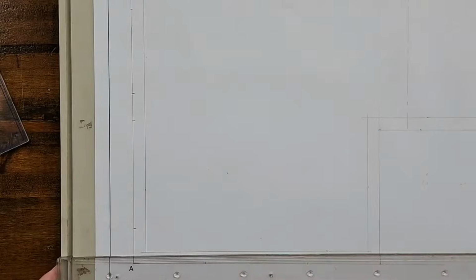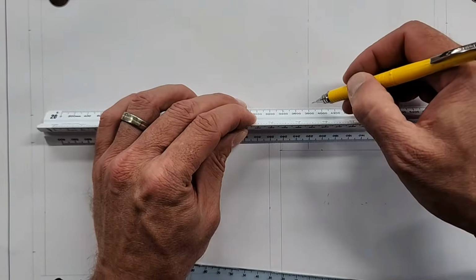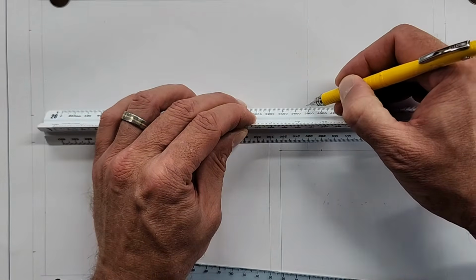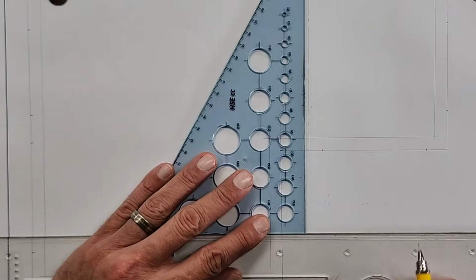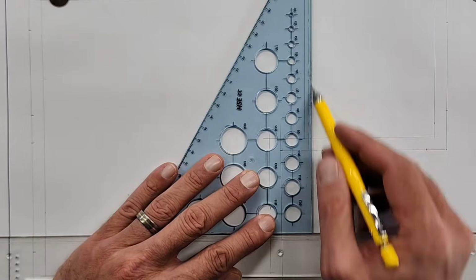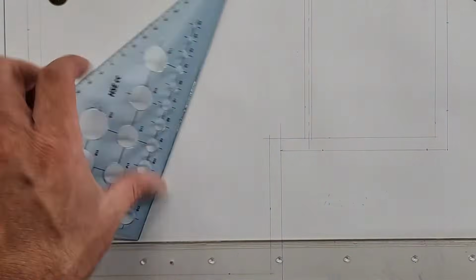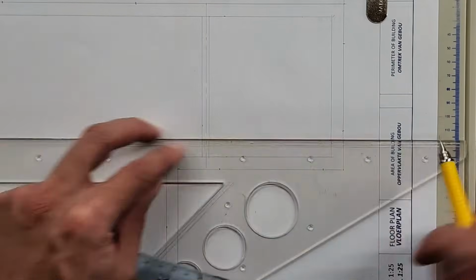Okay, so very quickly I've got the whole building framed here. The inner wall is going to be 110, which comes down to 4 millimeters. So that's going to be 2 millimeters on each side. And I can draw those lines in. The next thing before I do all of these lines nice and dark is I'm going to indicate my doorways and my windows. So if we start here, we've got a window.